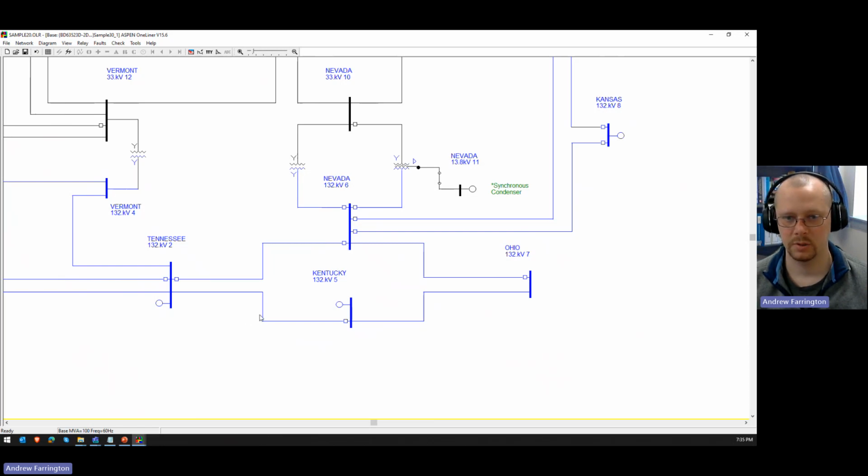Well, in this case, that wouldn't be your worst case if you're looking for security of that instantaneous element. You'd want to take that line out. Okay. So that kind of stuff, even if the standard says one thing, it may not actually be appropriate for your application. So that was a question I got, and I wanted to go over that.